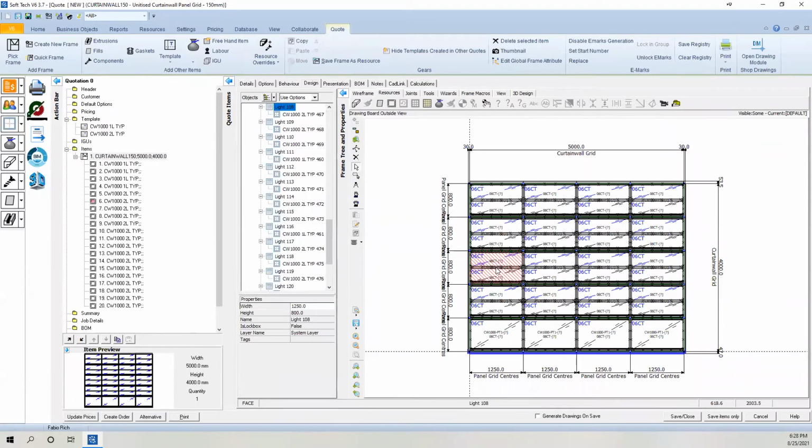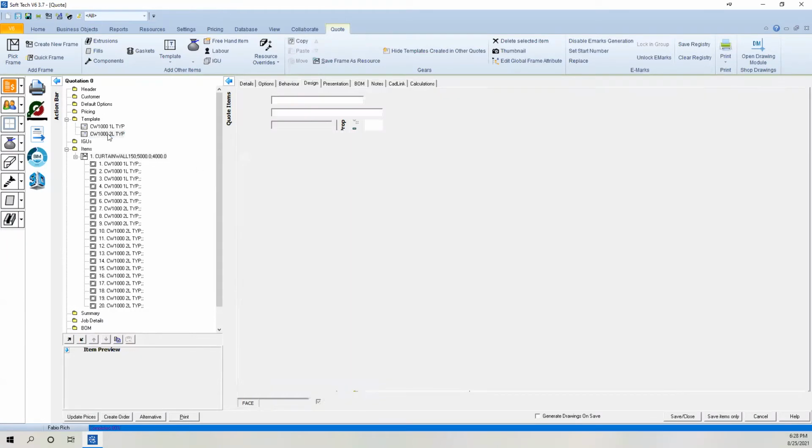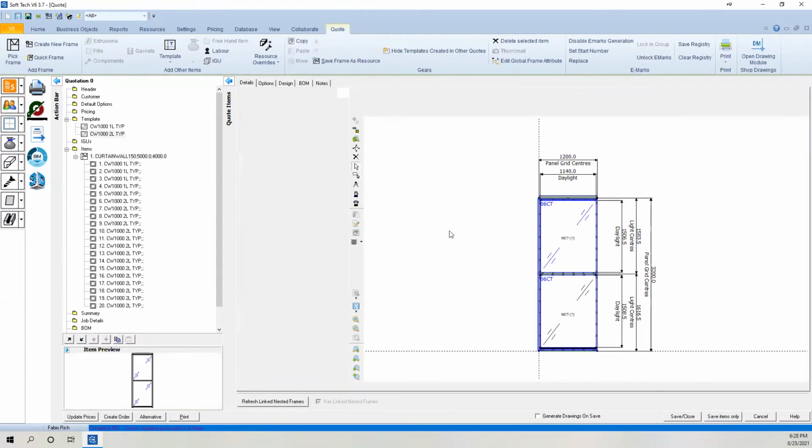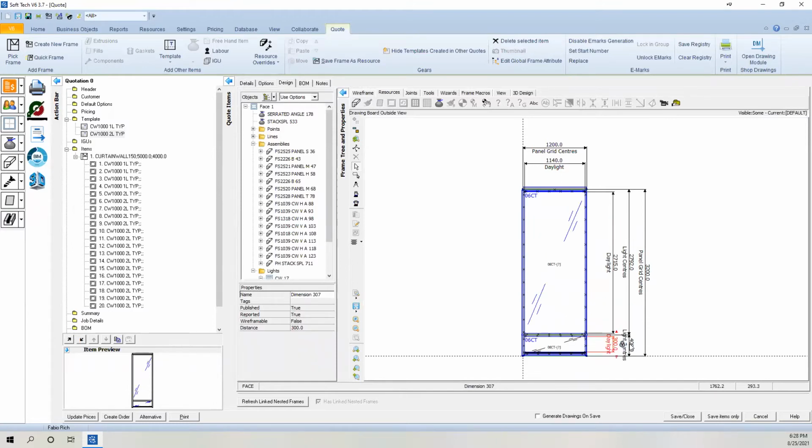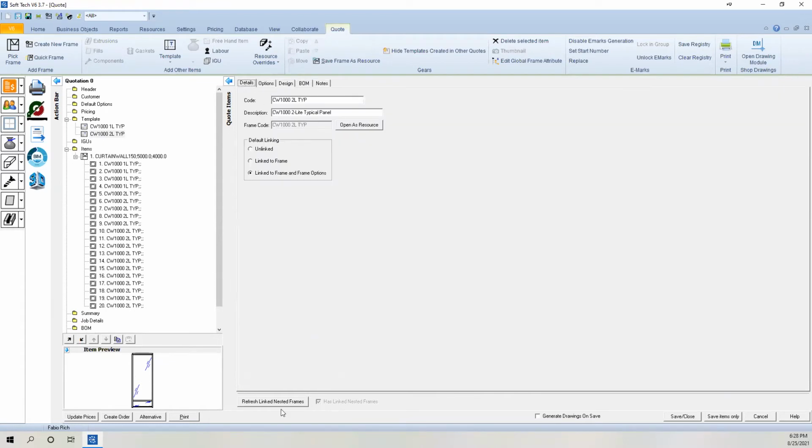So right now, the height of this, we can just check from here. So there is a defined height here. I'm going to change that to 300, for example, and lock that dimension. So this is locked. And I will go here and say, refresh everything linked to this.